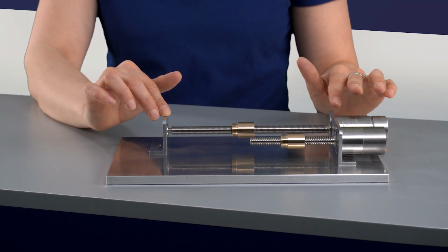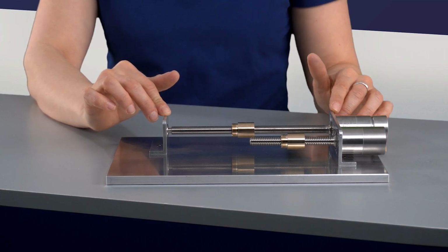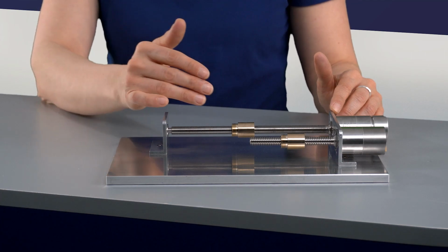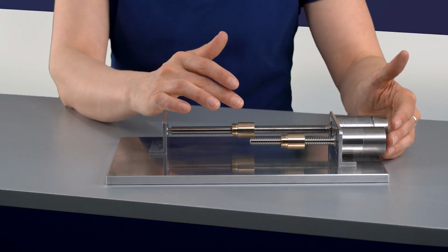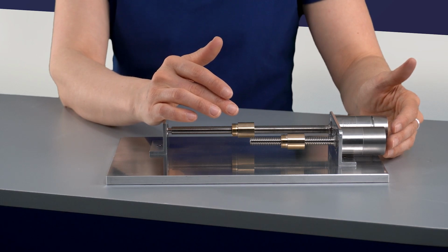You could use, for example, the option with the tip on the screw to mount a bearing at the end. Like this, it provides a radial support for the screw, but the thermal expansion of the shaft is still possible. This solution is ideal for longer screw length. The other method is the fixed free support, where the end of the screw is not supported. The mounting here is much simpler, but it is only recommended for applications with shorter screw length and slower speed.